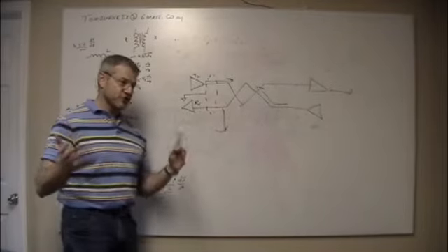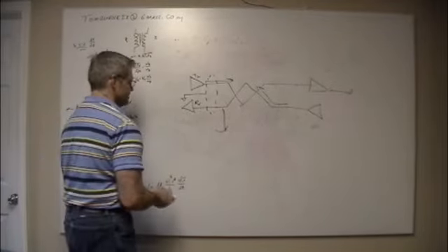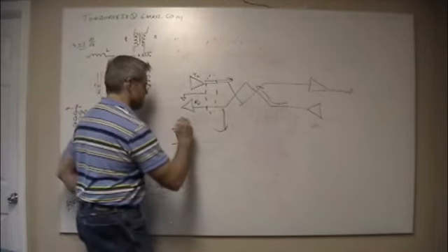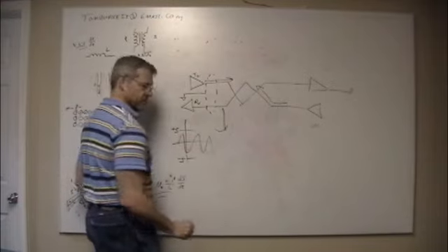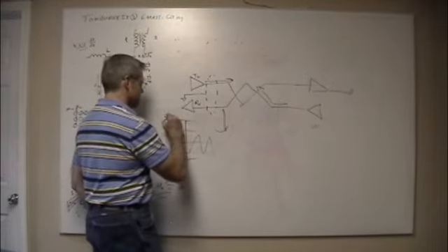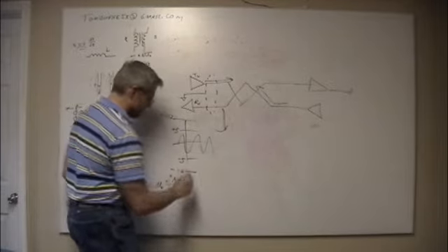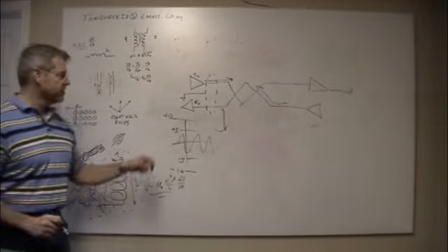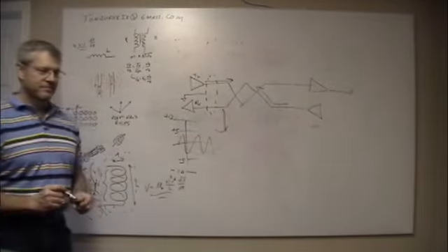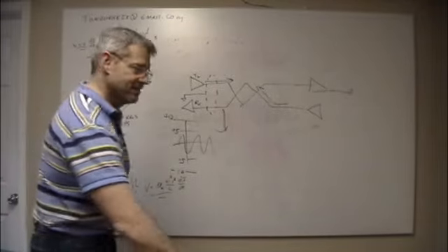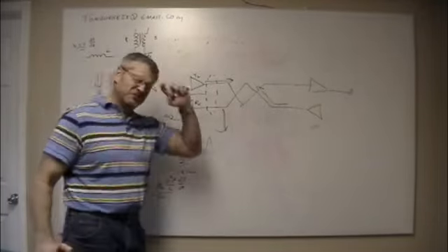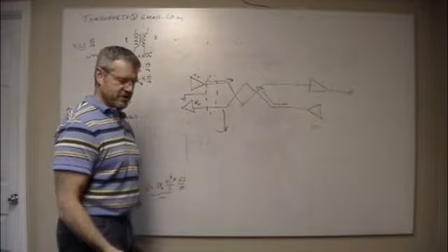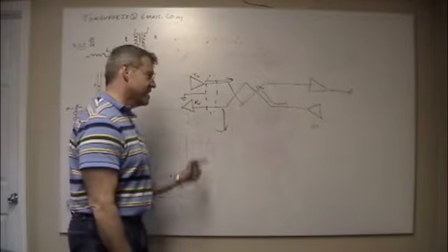Now, if you're using true RS-232, which has signal levels that are like -5 and +5, and this is an indeterminate zone and doesn't count, and it can go as high as +12 and as low as -12, maybe not such a big deal. But if you're using CMOS, 0 to 5 volt levels, that can be a problem. That can really screw up your signal. I've seen too many people do this. And I sit down and I say, you can't do that.